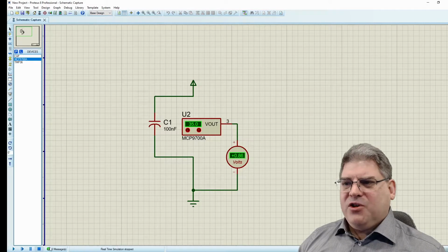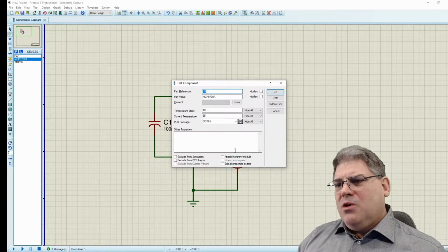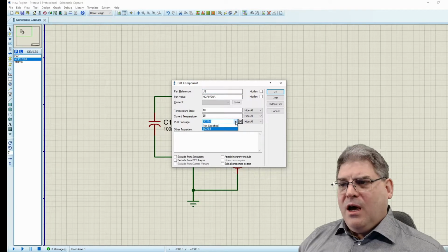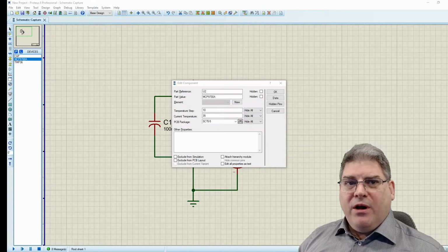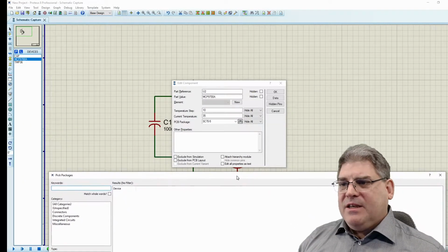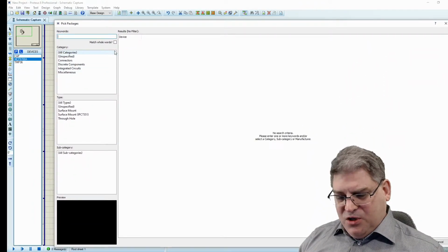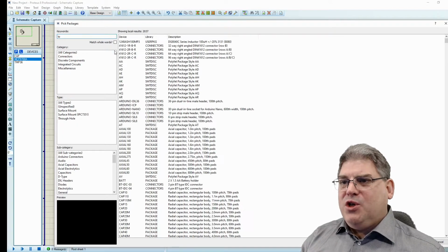And this is actually going to be the chip that we use in our final product. So you could drop this in. It's okay to use it. There's no problem there. But we do want to change the footprint at some point from this SC70, which I love that little package, but we want to change it to a TO92 case.